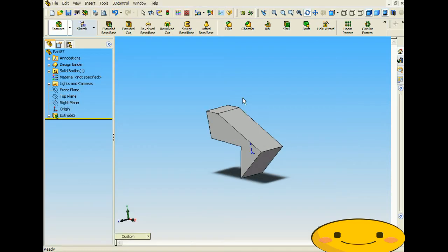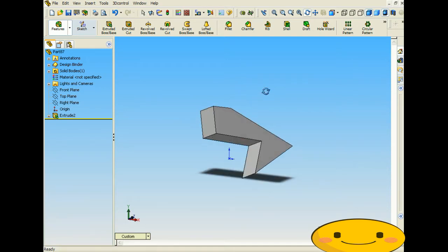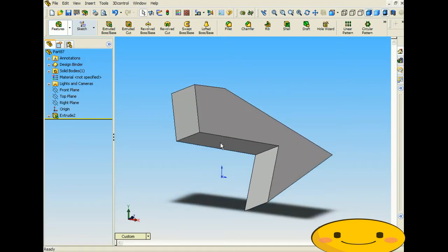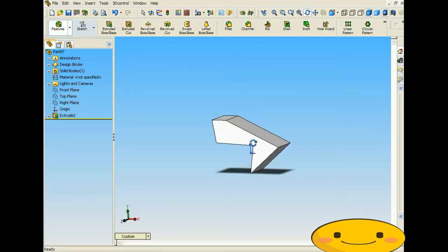Now you can use this tool either on a part alone or a whole assembly. So if you have a whole assembly and you put all your components into it, you're able to click it and see where in your assembly the center of mass or center of gravity would be. Now, when you're doing this, you have to make sure that you're using it on a solid. You can't use it on just a sketch alone. The sketch won't produce a center of mass or center of gravity at all. You have to have a part. And that concludes our tutorial on how to use the center of gravity feature within Solidworks.